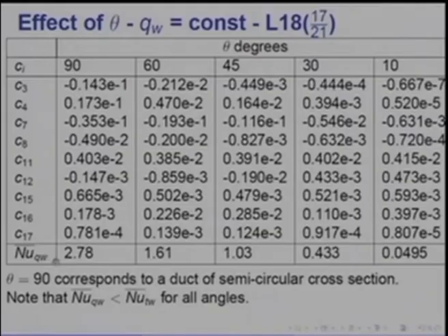So, now these values have been verified by finite difference calculations also. So, this is a very convenient way of developing solutions for uniform conditions. Now, of course, just to remind you, I have taken circumferentially uniform wall temperature and circumferentially uniform heat flux just as special cases, but you could well have any arbitrary variation of Tw and Qw, and still we would get the solutions exactly in the manner I have described.